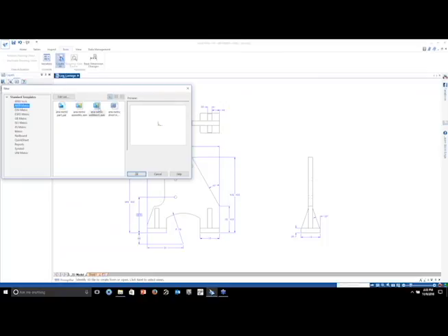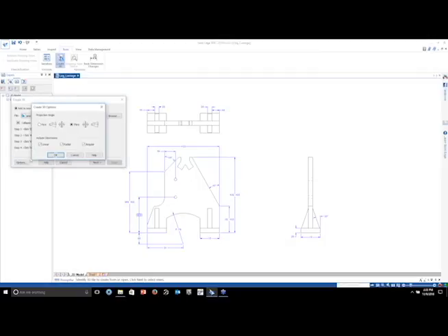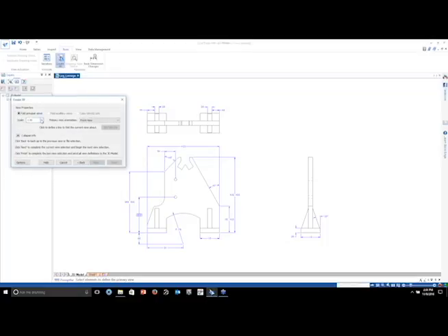All right, under the options, let's use third-person projection. That's what we use here. And of course, if you don't want dimensions to come across, you can uncheck these. But if you do want them to come across, have these checked. Say OK. All right, so scale, I turned the title block off, but down here you notice it gives me a scale value. I'm 1:1, so I know I want to leave my scale at 1.